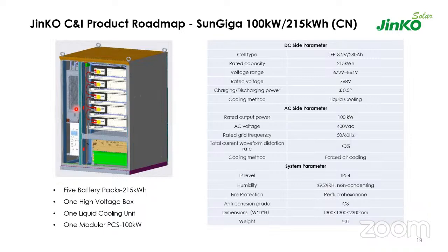This comes as a solution with a liquid air cooling mechanism, which is why the auxiliary consumption of this solution is far less when compared with forced air cooling systems, and the levelized cost of storage of these products is much lesser when compared with forced air cooling systems.